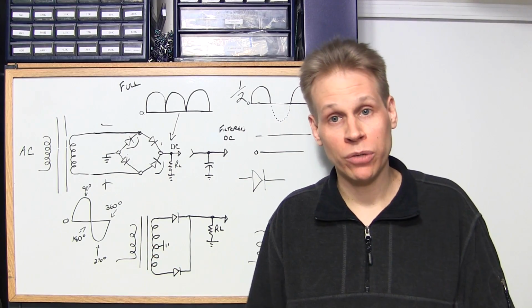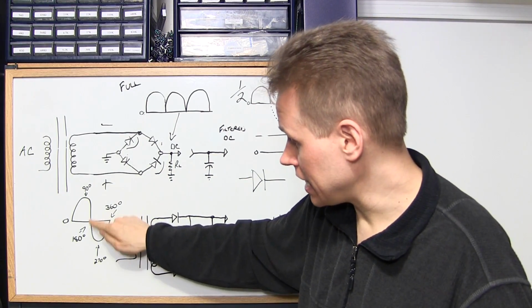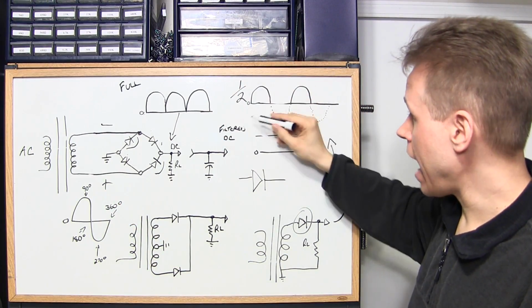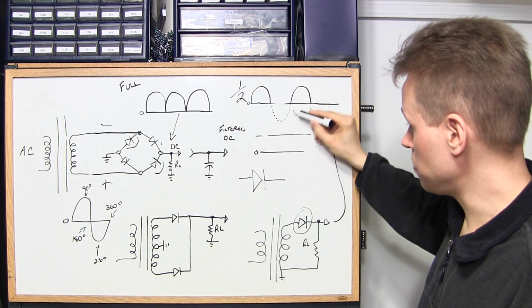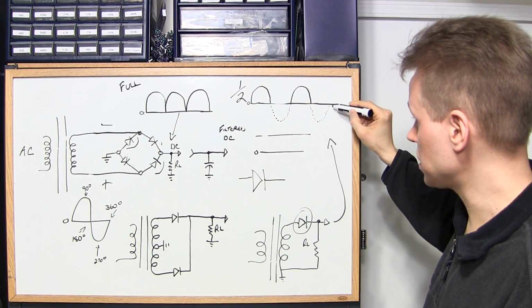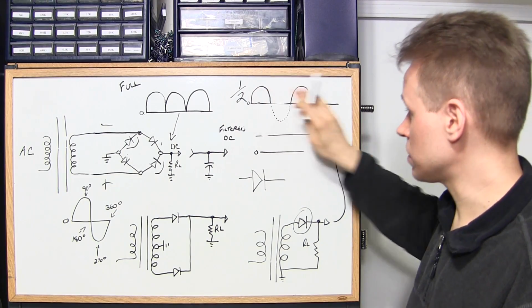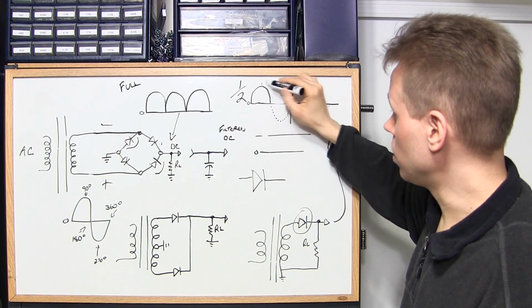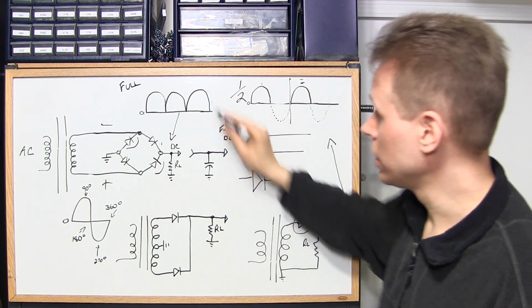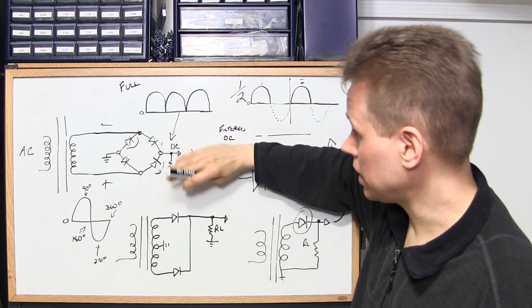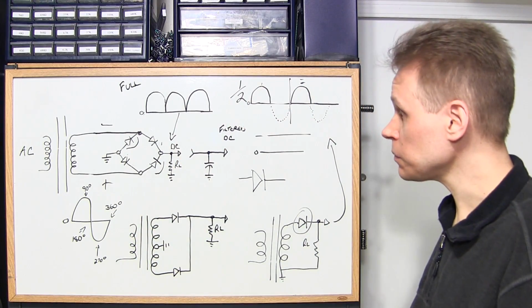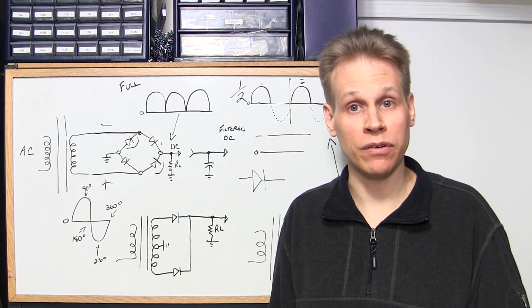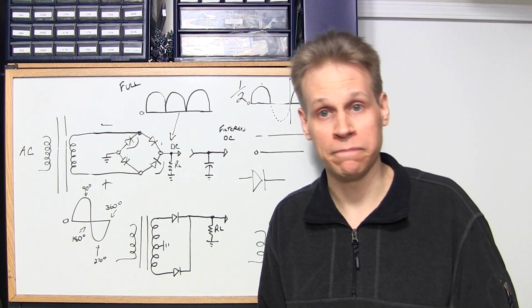Now this is acting as a frequency doubler, because what it's doing is it's taking this half of the cycle and putting it up on top. So instead of having, for a half wave, this here, and then of course this is missing, and then we have this one here, and then this is missing here. This is 60 cycles still, because this is one full wave right here. So it's counting this as 1 and 2 and 3 and 4 and 5. This is taking the bottom half here basically and putting it up here as well. So we get a frequency doubler out of that. So that's why you hear 120 hertz buzz out of a full wave rectifier if the capacitors are bad.